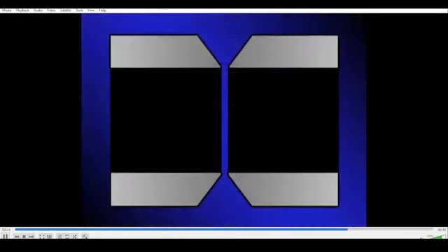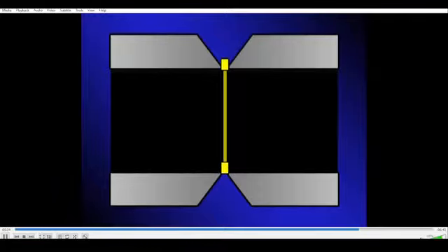When a K or Grinnell type insert is used, the insert is sometimes allowed to extend above the root edge in the flat portion of the pipe and below the root edge in the overhead portion. This procedure compensates for sagging of the molten metal due to gravity. When welding with automatic gas tungsten arc equipment, an extended land is commonly used with a zero root opening. In this manner, the root pass can be produced without the addition of filler metal.